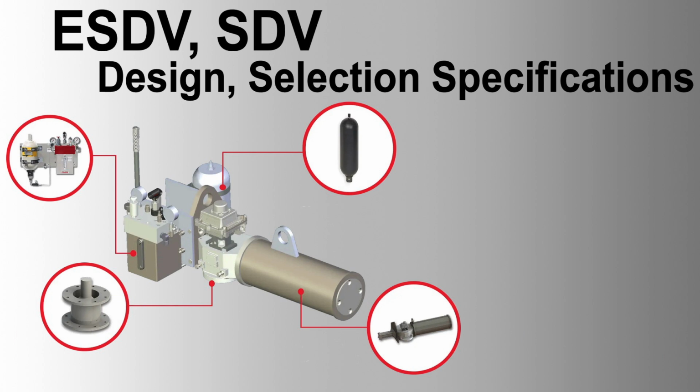Actuator general type: pneumatic piston spring return quarter turn type. Construction material: carbon steel for diameters 2-inch and above, aluminum for smaller sizes due to weight support considerations. Operating conditions: must shut off against the maximum differential pressure and be suitable for open, unprotected environments. Weatherproof standard: IP66 minimum. Tubing and fittings must be SS316L with a minimum size of 1/2 inch OD. Fittings should be of Hoke Gyrolock double compression type.